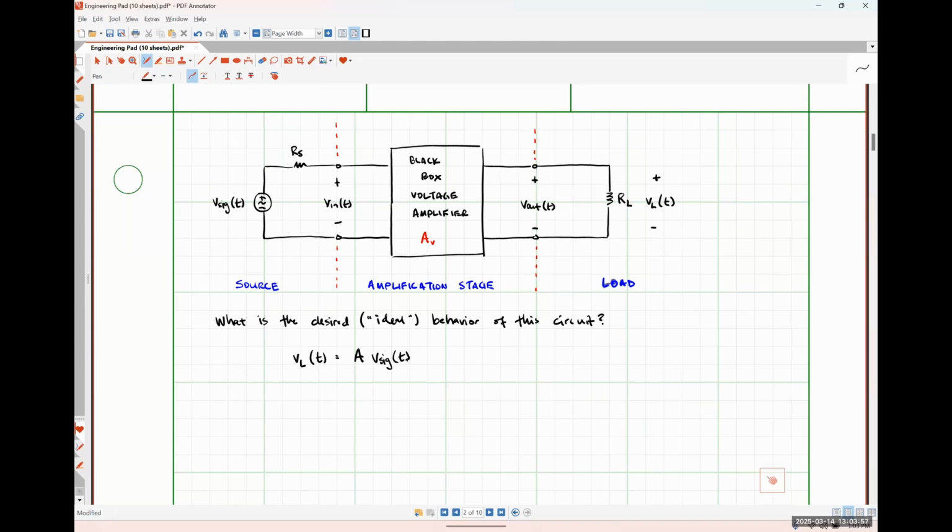So we're trying to effectively get a Thevenin equivalent circuit. So if we have no voltage source connected because we've turned it off and we look into the terminals, what are we finding? So we would find a Thevenin voltage of potentially 0 volts or something like that.